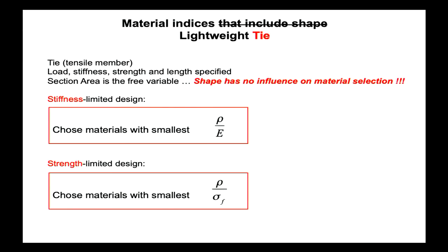And what's nice is that when we look at ties, that is axial tension, and I've got this big strike through that, there is no shape influence on ties, which I'd hope everyone would think, yeah, that makes sense. Other than edge effects, stress equals force on area, why should the shape of the object really have a big impact?